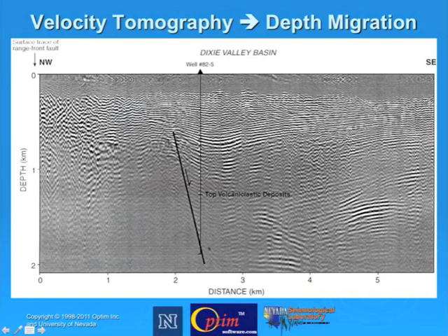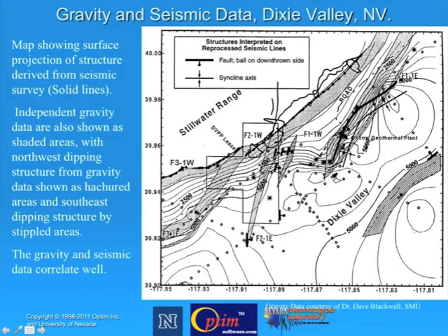And it's these basin-ward faults in Dixie Valley that we first noticed as really providing the sites for the best injection wells and the most productive production wells. So here's a look at the gravity contour map, and you can see that there are faults located with the seismic analysis, and faults located via these gravity gradients, the places where the gravity contours are a little bit tighter.